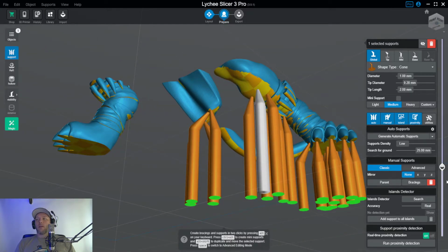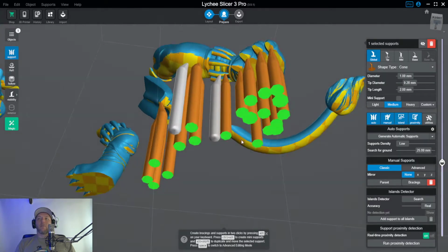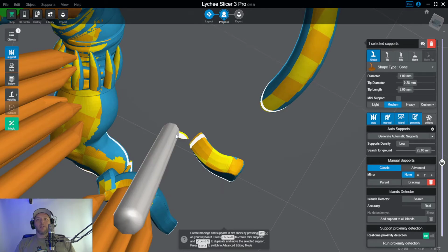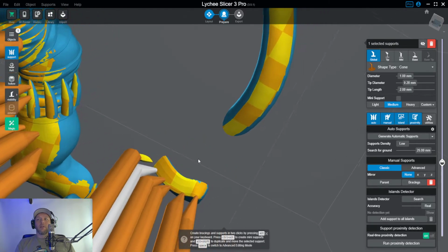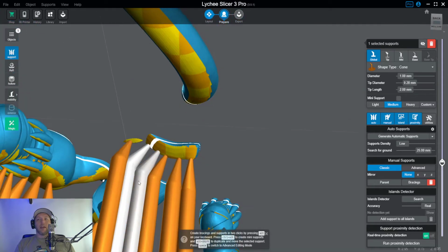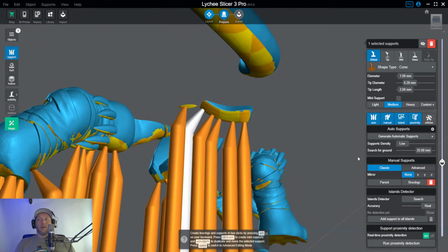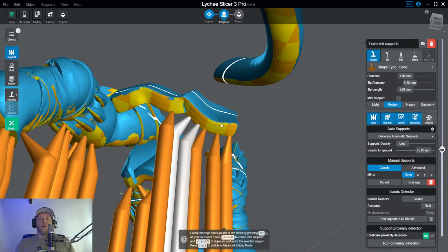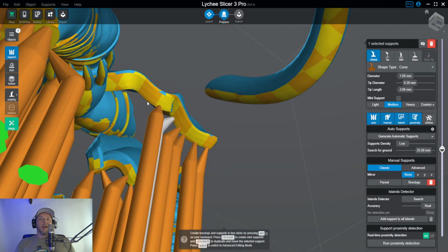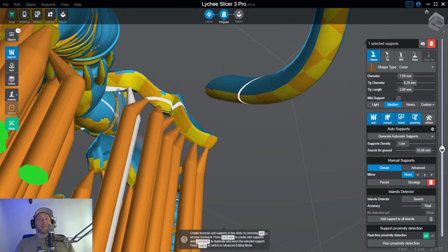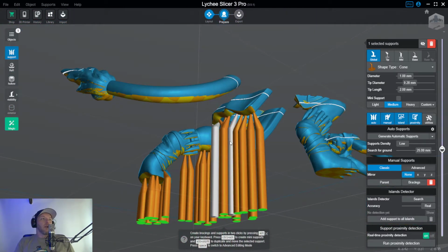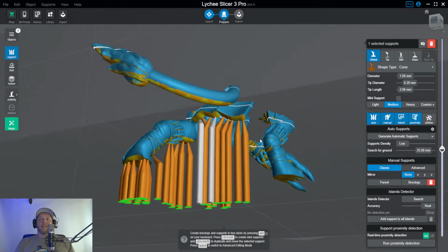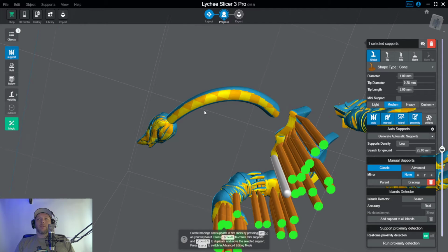So now we're working our way up the leg. We're looking for more islands. We're starting to see more here, so we're going to need to start adding in supports. We're going to chase that edge. That looks pretty okay. This might be overkill, but I know on these loincloths, they always seem to pull. I put 2 supports, 3 supports on it, still pulls off the supports, so I go a little overkill. But I know it's right on the edge. It's going to break clean, and I've got good enough settings and tuning that we should be okay.